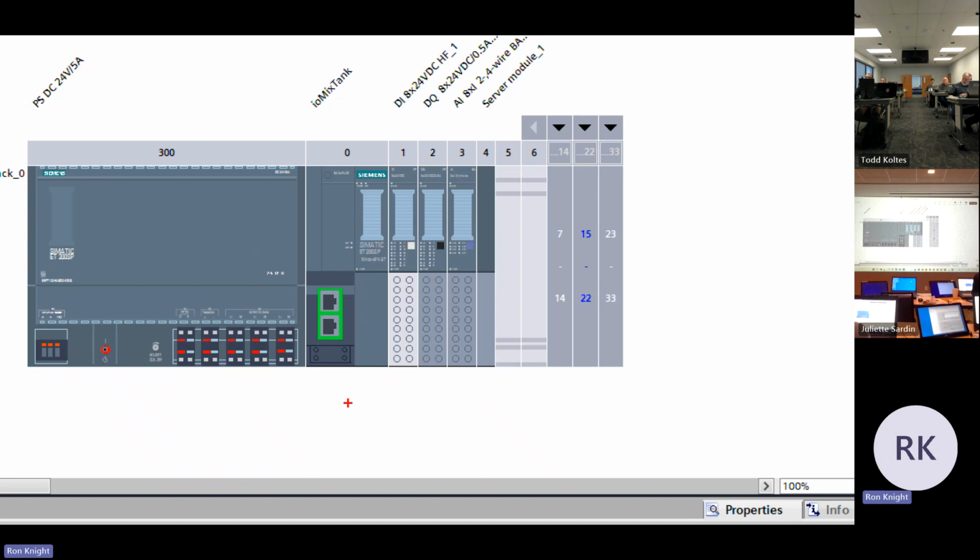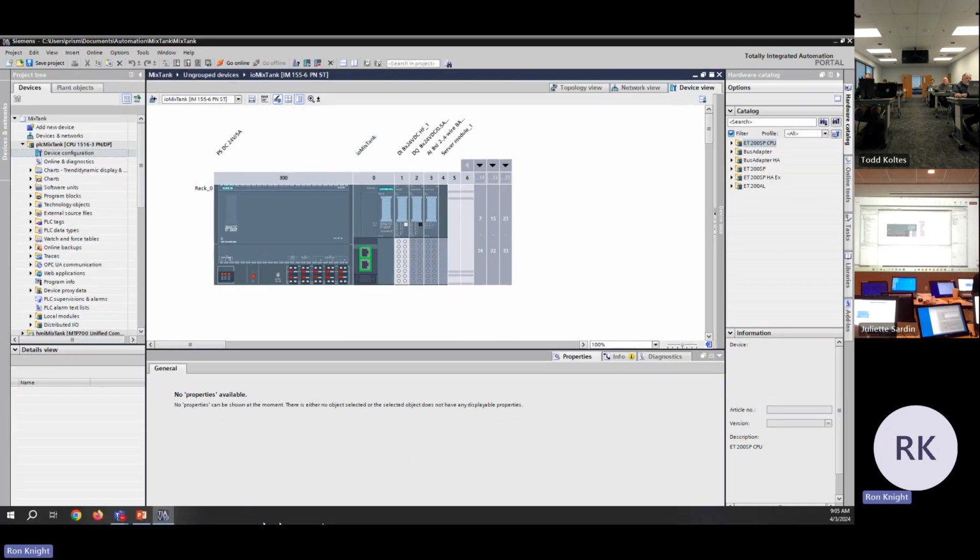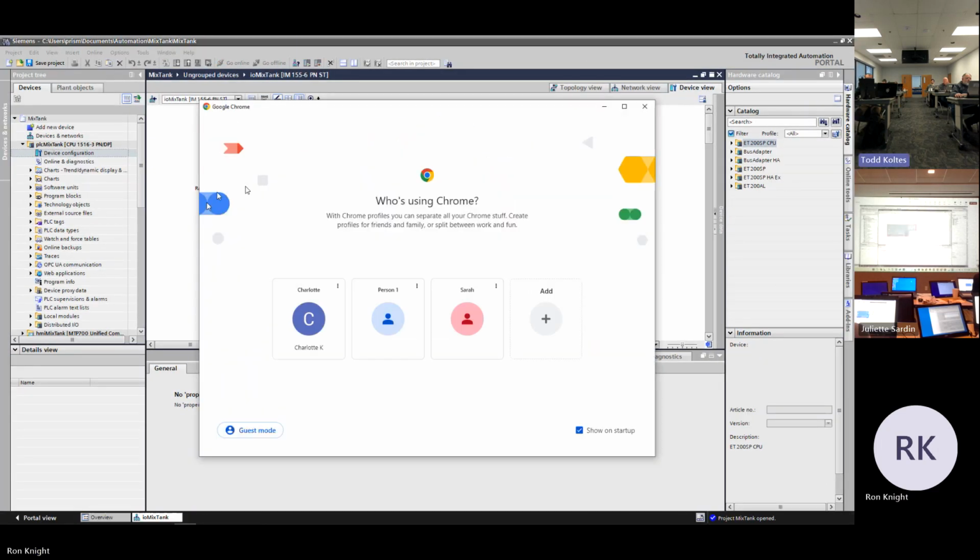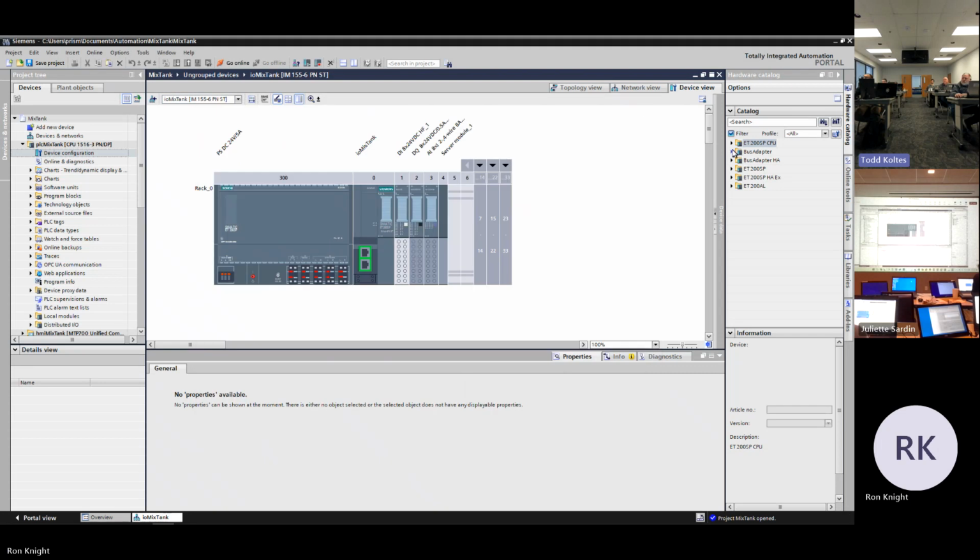There's one called an MFP, I think is what it's called, and that one you can actually do Modbus TCP, Ethernet IP, or Profinet, I think, all in one adapter. Correct. And all three at the same time, interestingly enough. We could have Profinet talk to some modules, TCP IP talk to other IO modules, and then Ethernet IP talk to others. You can mix it up all in one station. Yeah, it just came out a couple of years ago. It's pretty slick. It's crazy.